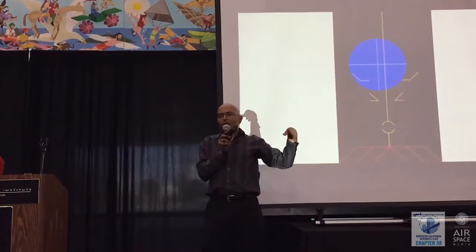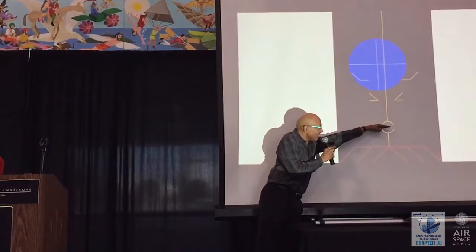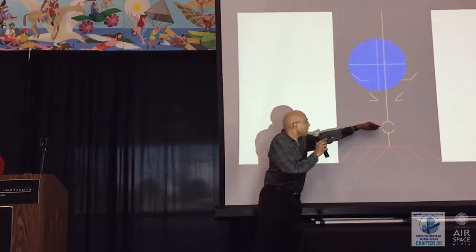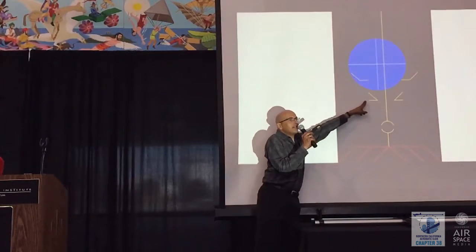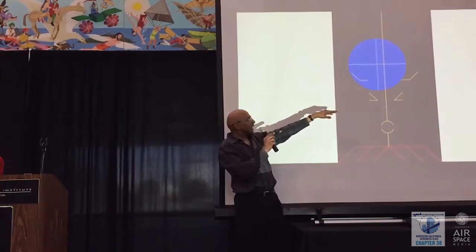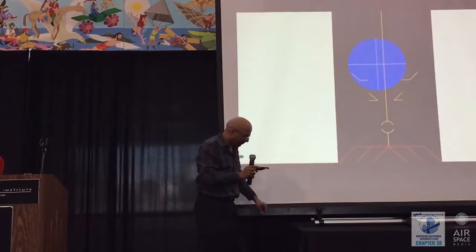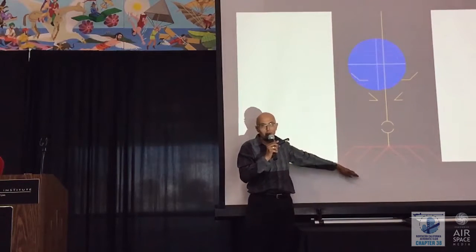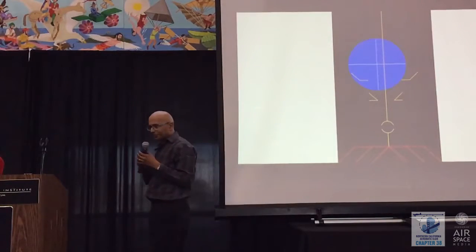There are a bunch of annotations that we've come up with to put on this display. This is your reference angle of attack for landing approach. Because it looks like ramps, this is your best angle of climb angle of attack. This would be your best rate of climb angle of attack. And this we call the cow catcher. This is where you don't want to go. This is your stall angle of attack right there.